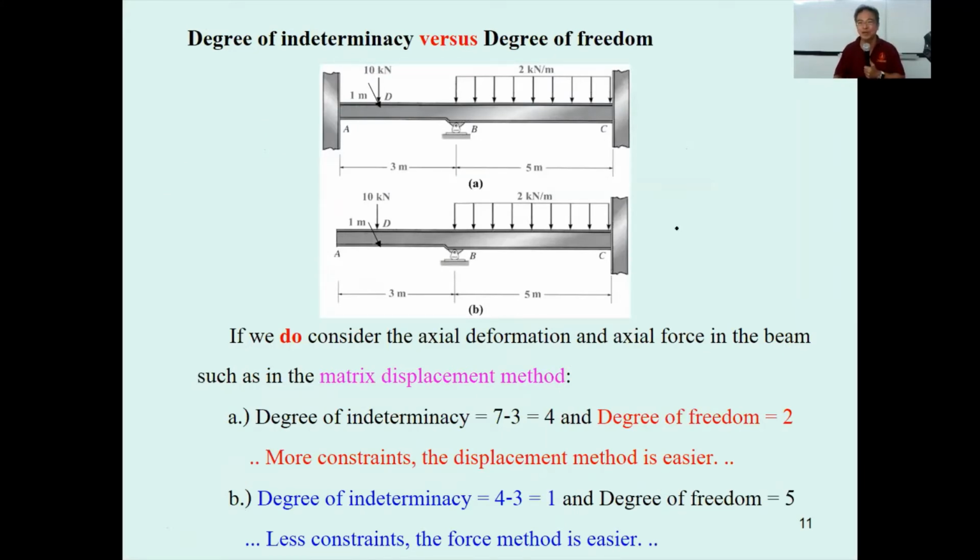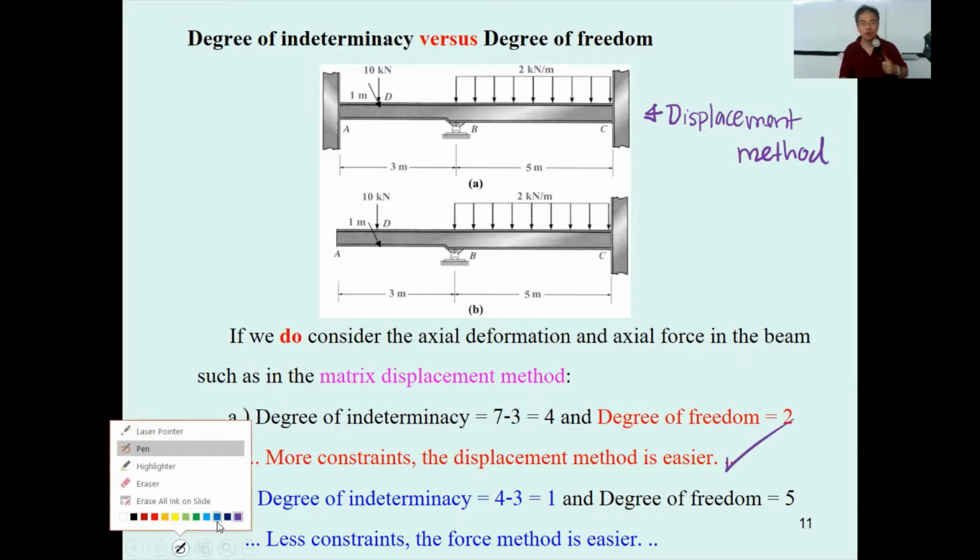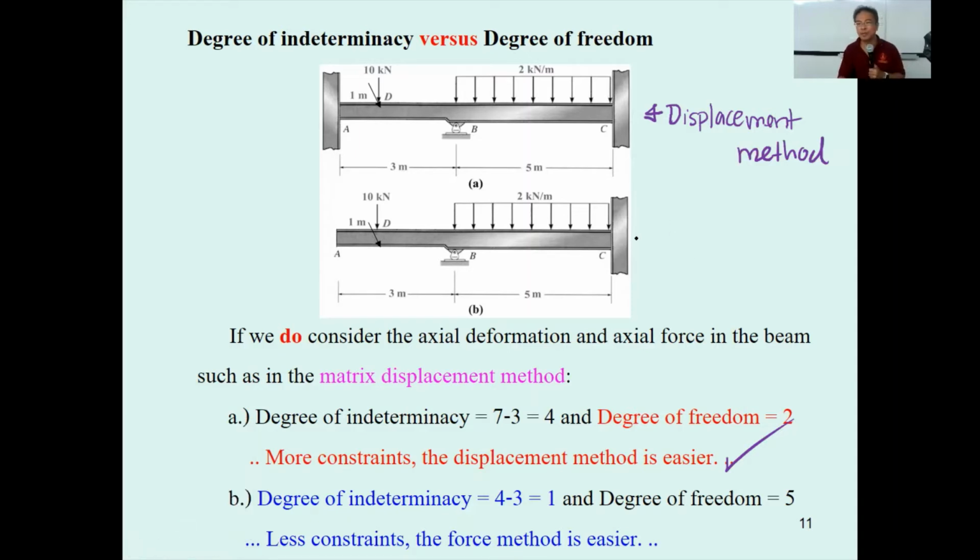Okay, review again. For this problem that has a lot of support, this one will be so much easier when you use the displacement method, following what I mentioned over here. But when you come to this kind of problem that has less support, the force method is going to be a better choice for you to use.